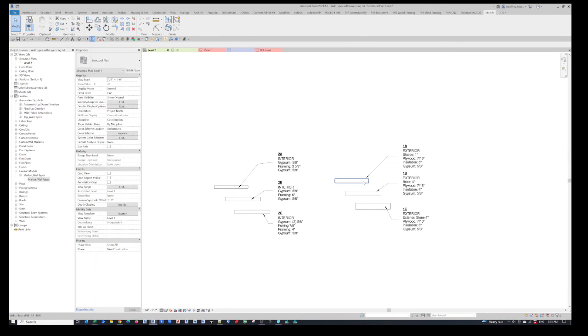Anything that was not impacted will remain the same. So it gives you a very robust methodology to also handle all of your tagging, and you only have to place one cube on a per wall basis wherever you want to actually tag. So maybe there's only 15 different key locations you want to tag out on a project. Just place those where you need and be done.